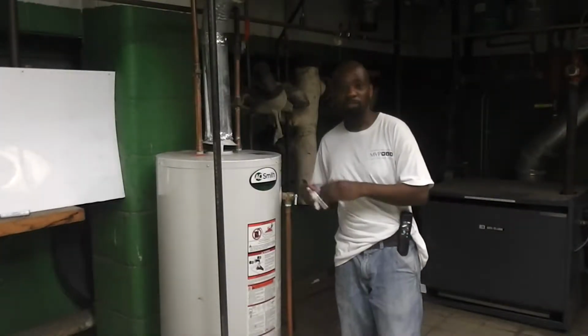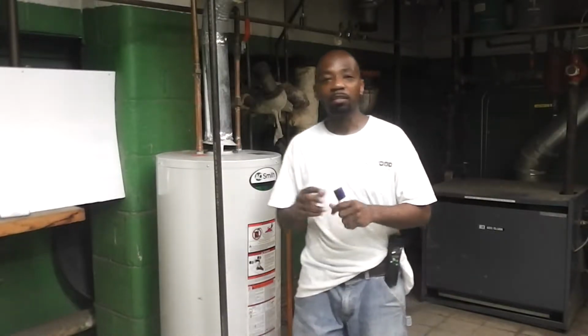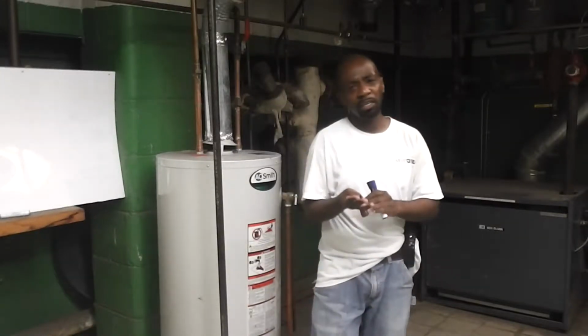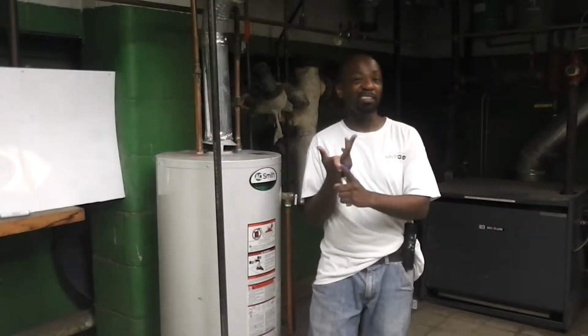I'm here today to show you how to do a combustion safety test within your CAS, or your combustion appliance zone. The test consists of four different tests actually: worst case depressurization, spillage, draft, as well as measuring undiluted CO.